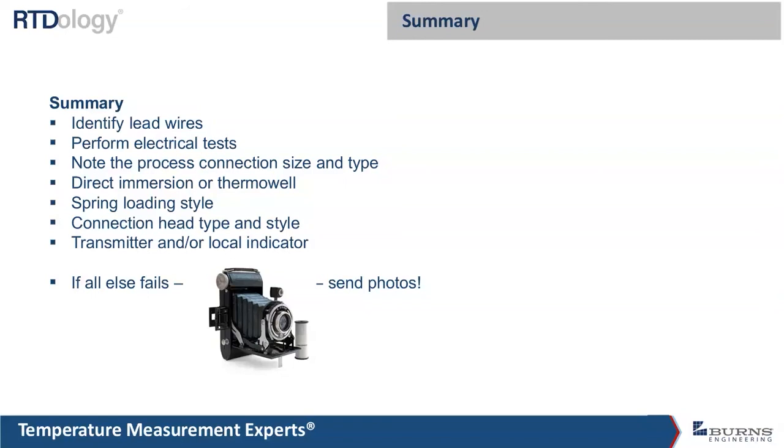If we're looking at a Thermowell, or even a probe that may be immersed directly into the process, we need to know the connection size and type, whether it's threaded, flanged, some type of sanitary connection. And probes that go into a Thermowell, the spring loading style.